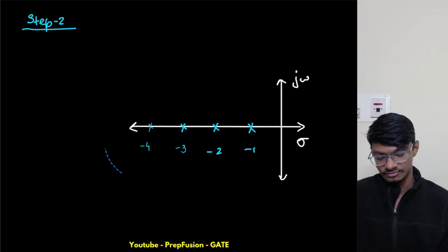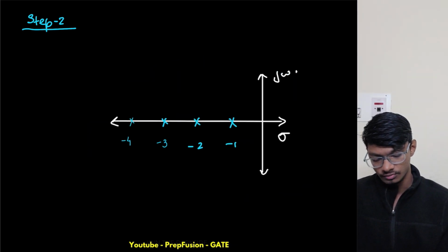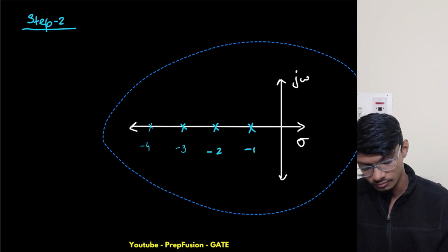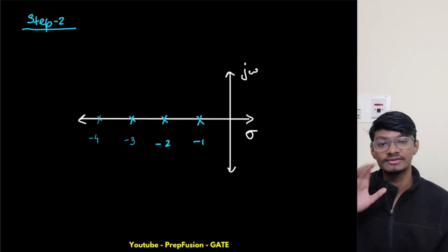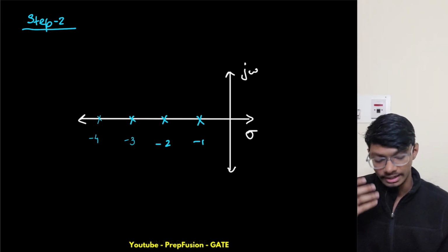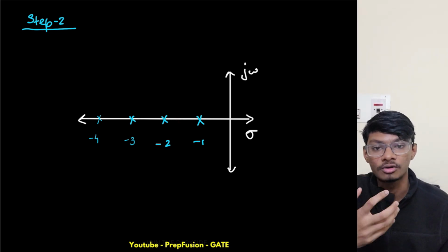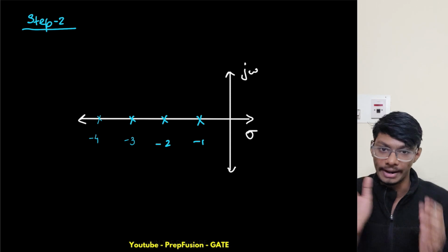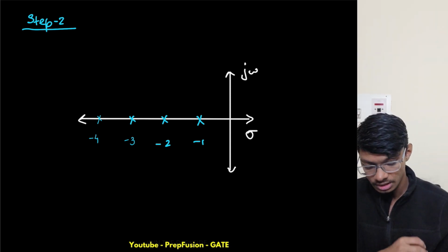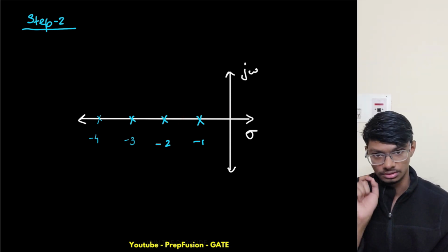What can I see from here? What was the rule that you used to follow? It was the angle rule, but it has been refined so that on the right hand side of my test point I should have an odd number of zeros or poles, the addition of those. So here what do I have? I have one pole.